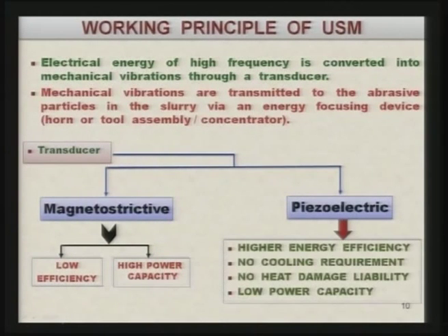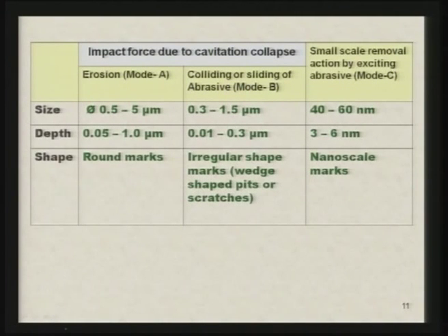On the other hand, you have the piezoelectric type of transducers. They have higher energy efficiency, they do not require any cooling, there is no heat damage liability, and the problem is their power capacity is low. In case of magnetostrictive type of transducer, most of the time you require cooling. So, that again adds to the cost of the whole system.